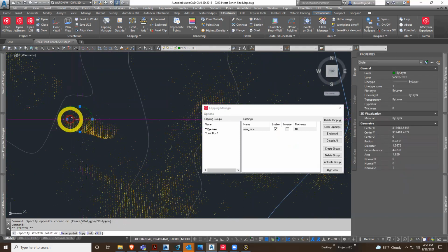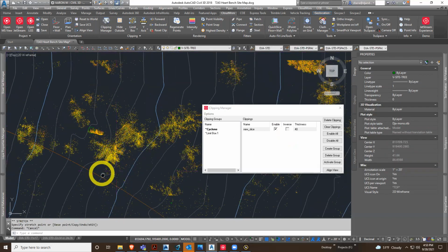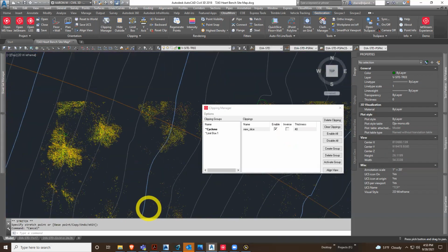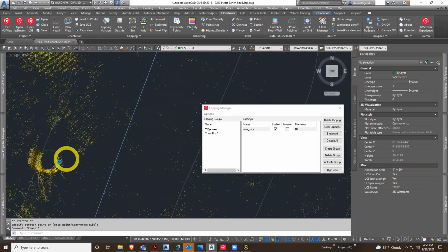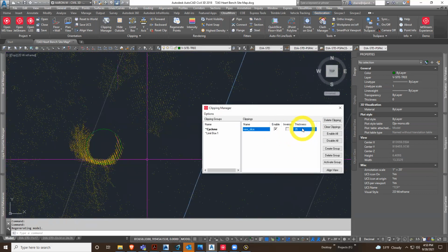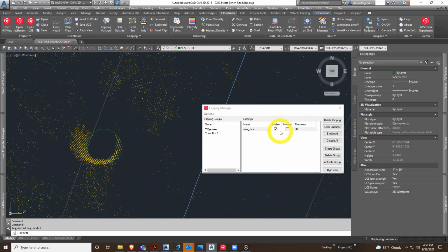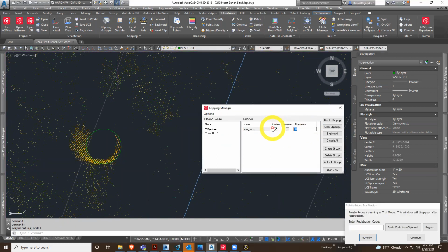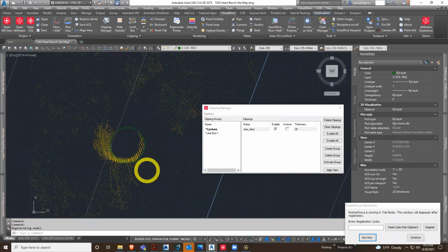Sometimes they're hard to identify like that. Sometimes they're really obvious and right in the center, like this one here. This one's pretty obvious once you get the right slice thickness. So if we went a little thinner there, move it around, it's going closer and closer to the ground as it goes in the negative Z direction, because that's how I established it, remember, at the beginning. If you go on to 20, it should almost be gone.